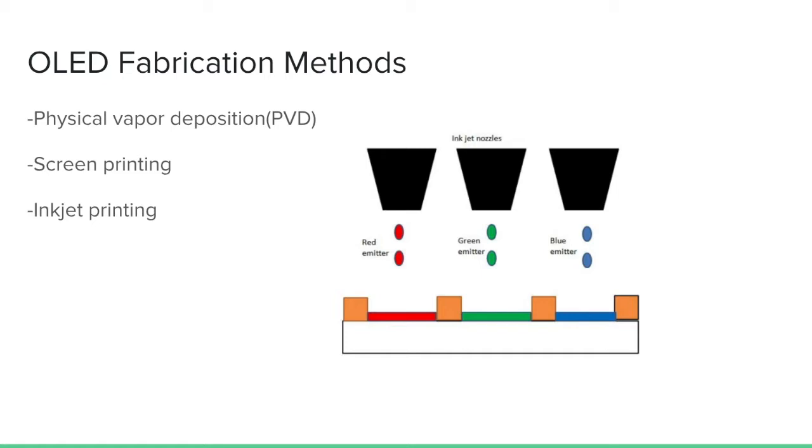This can be done with a sample of an ion beam from an external ion source. Thermal vapor evaporation of small molecules is carried out on a glass surface. Multicolored displays are made by properly aligned shadow masks for depositing RGB emitting material.